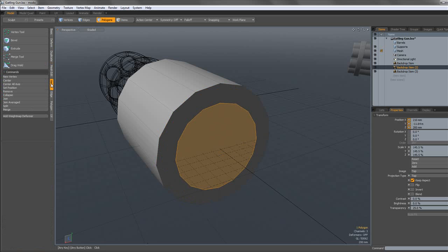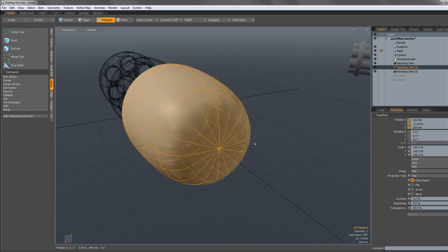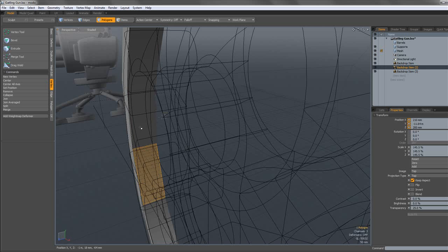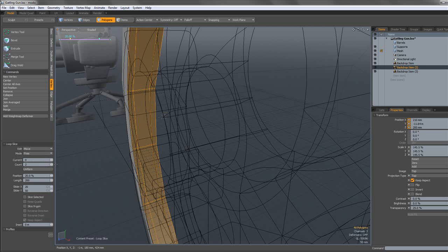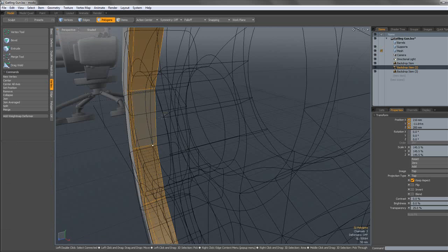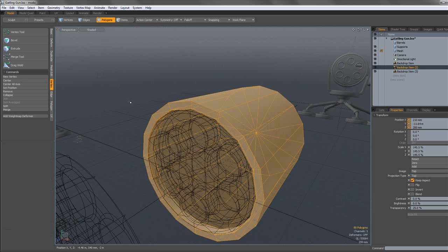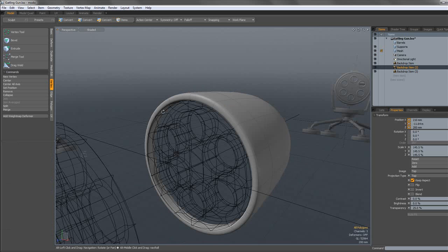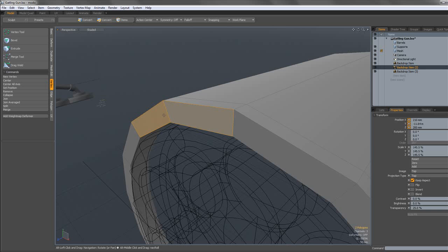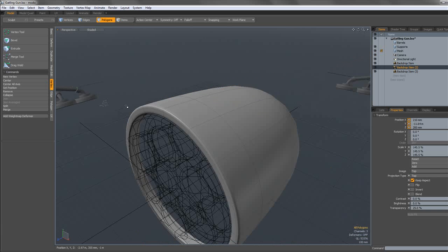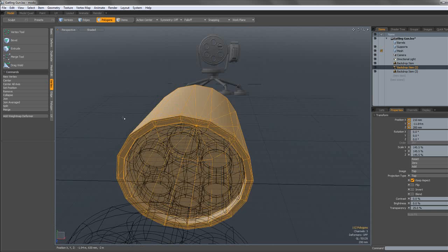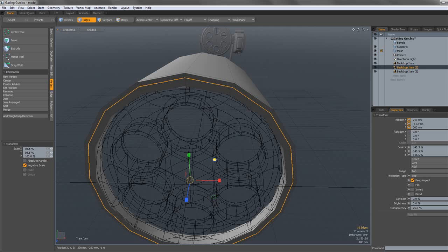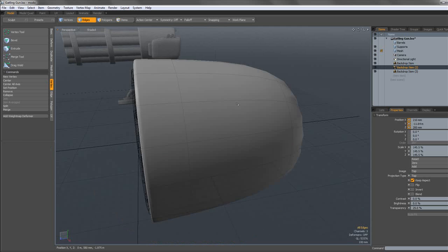And just bevel in, go to vertex and join averaged. Now right out of the box, if you smooth this, you're not going to get what you want, so again we're going to have to add support edges along the way, and we're probably going to need one up here. Let's see if we add one. Yeah, this works, but sorry, it needs to be a bit further in.